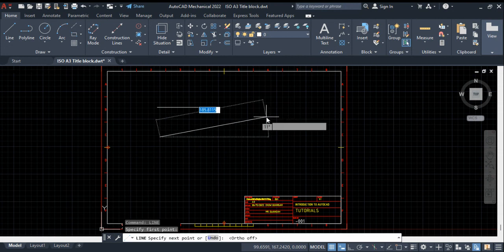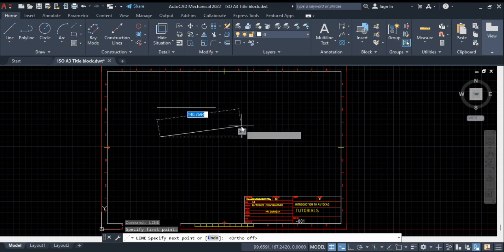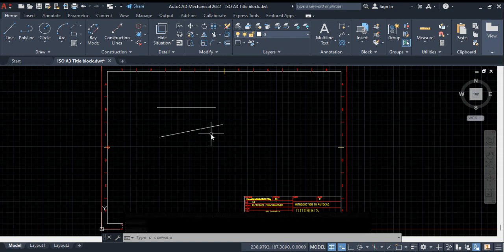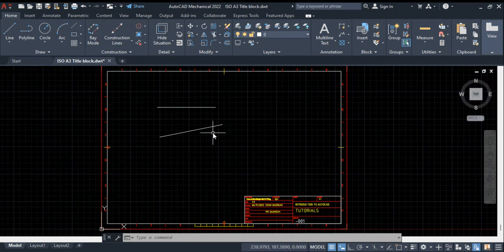So I want to draw an inclined line at an angle of, let's say 12, but a length of 110. So if I want to switch, what I need to do is to press tab on the keyboard. If I press tab on the keyboard, I switch to the angle and I want to draw relative to the starting point an inclined line at an angle of, let's say, 12. Then I switch back, then I enter my length of 110, press enter. Press enter again, then I've drawn an inclined line and it is measuring my angle at 12 from the east. Remember from the unit settings we did.